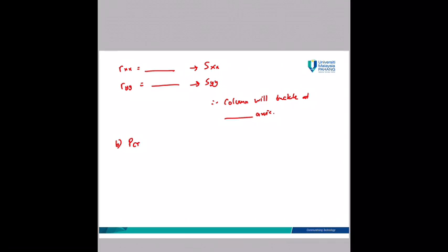After that, you calculate your RXX and RYY. And from here, you calculate your slenderness ratio. Then make the conclusion. Column will buckle at what axis? So you're done with question A. Question B is a Euler buckling load, which is a PCR. You calculate for PCRY and PCRX.